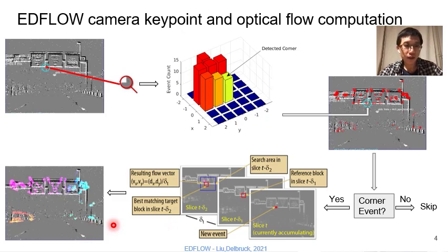The output is a stream of optical flow vectors along with its original DVS events. And the feedback control of the slice exposure is to keep the average optical flow length in the center of the multi-scale search area range.